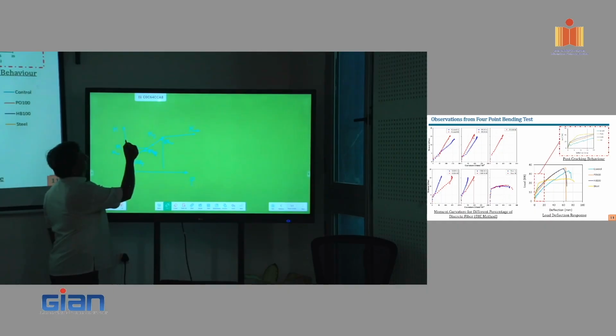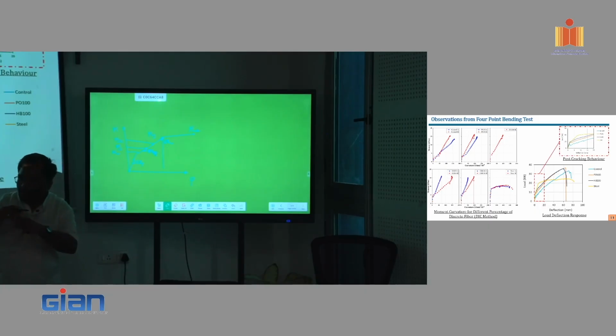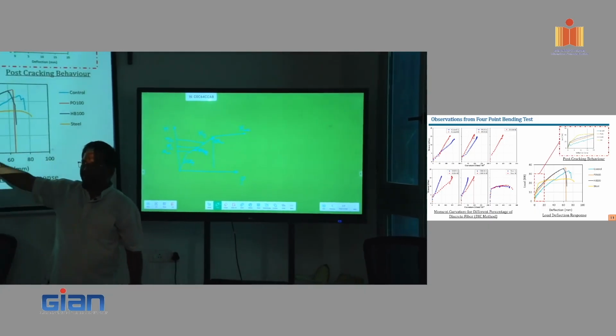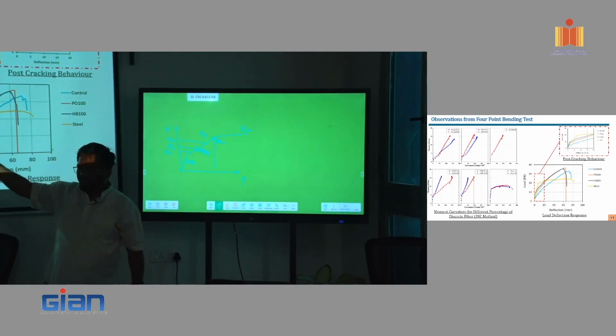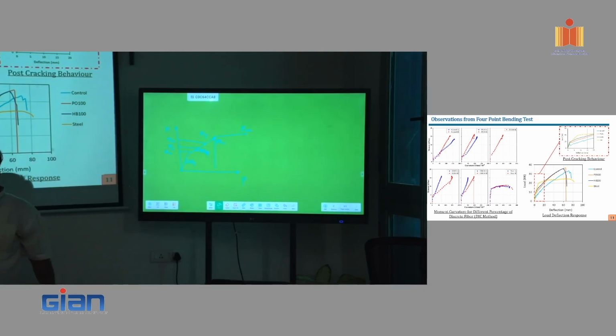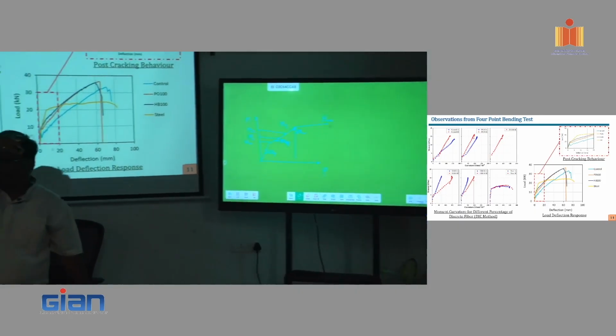Let's say this is M1, this is M2, and so on. Now, for this M1 and M2, I need to know how far I am away from M cracked, right? That is the reason in the equations I get M cracked. But M cracked is given to you. The moment you know your tensile strength, I know what is M cracked. But the higher I am away from my cracking moment, the closer I get to I cracked.